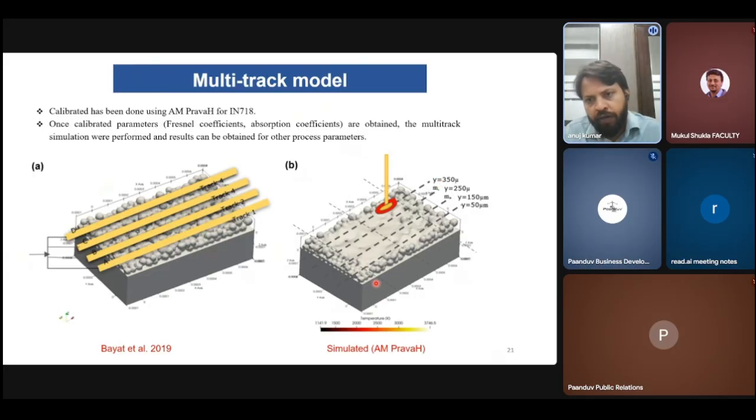So whenever we think that a part has failed, right, we made a multi-layered part with this process and it got delamination, the part lifted from the substrate, and there was lack of fusion, when you studied its microstructure you saw some pores in the structure, and you go back to the process itself. That is one way.